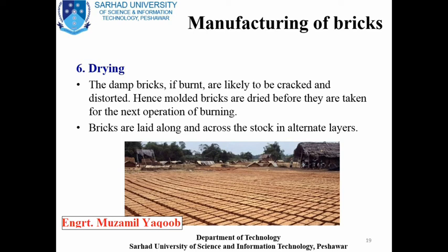Before burning, it is essential that the bricks have dried and become sufficiently hard to be handled and stacked in kilns. For drying, the stacks are arranged in such a way that sufficient air space is left between them for the free circulation of air.